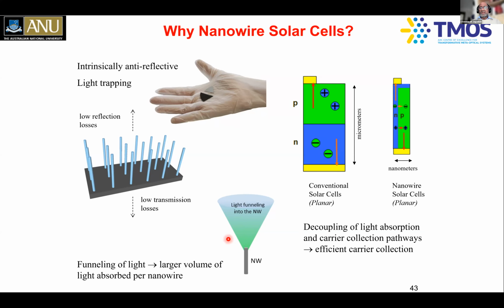Again, the challenge is how to make contacts. And then when you take these nanowires and fill this with a polymer material, like in this case BCB, and selectively etch this using plasma etching, put some indium tin oxide contacts and the metal contacts at the bottom, thereby light can transmit to this indium tin oxide transparent conducting oxide. You can see the top contact, and you can see the nanowires here at the bottom contact here.